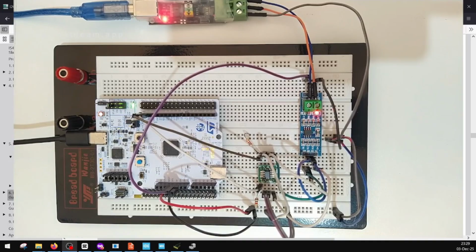So if it's possible, use a 5 volts transceiver. And there is no problem with the interface to the Modbus chip because the Modbus chip is 5 volts tolerant on the UART connection to the transceiver, and it's also 5 volts tolerant in the case you are using a 5 volts microcontroller. So the I2C and the UART pins of the Modbus chip are 5 volts tolerant, but the chip goes to 3.3 volts.